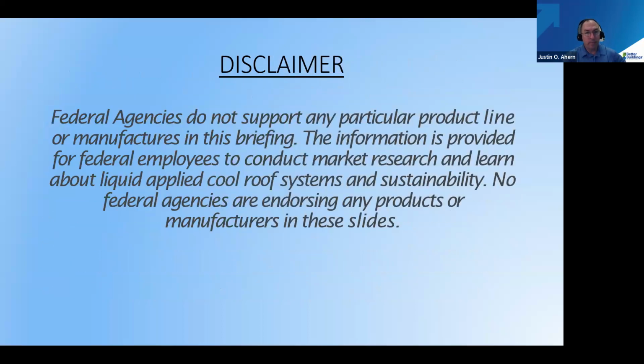Next slide. A disclaimer about what the VA selected. There are many products out there by many suppliers in your area. Not all are built up systems. We selected a cool roof system manufactured by Instacoat Premium Products that met our following requirements. This is the type of emerging technology with roofing systems that allows for rubber emulsion with an 800% elongation property of expansion and contraction. This is a base coat of elastomeric rubber. It's self-healing, self-sealing. If cut or punctured, it seals around the penetration or sliced area.